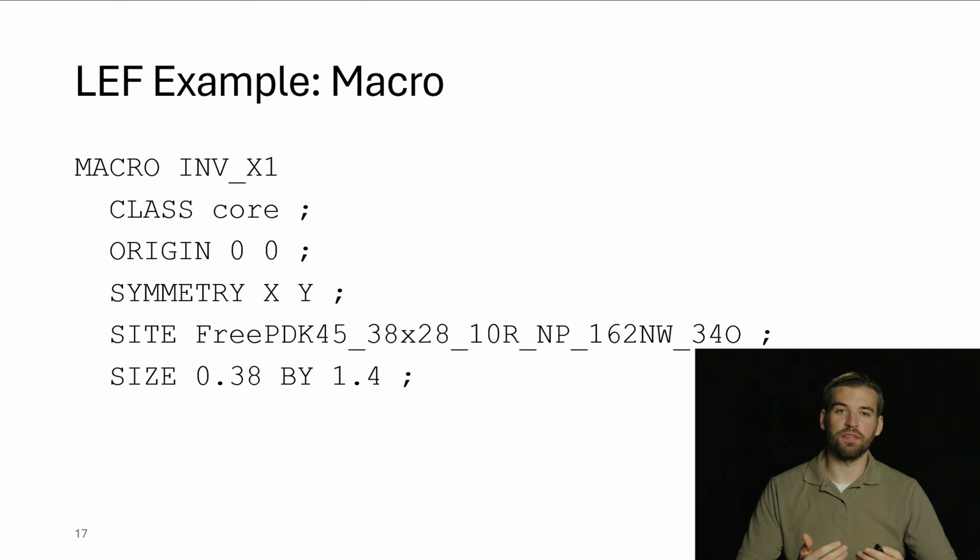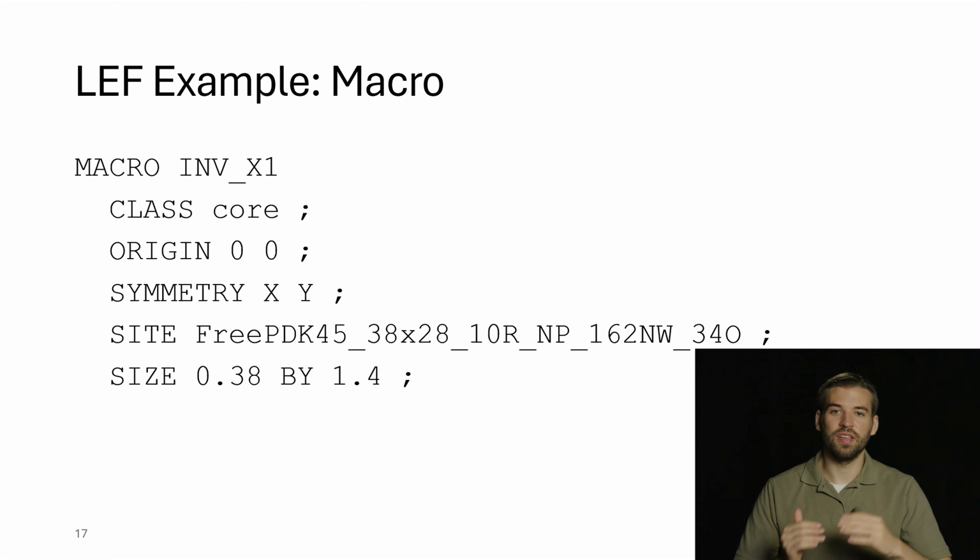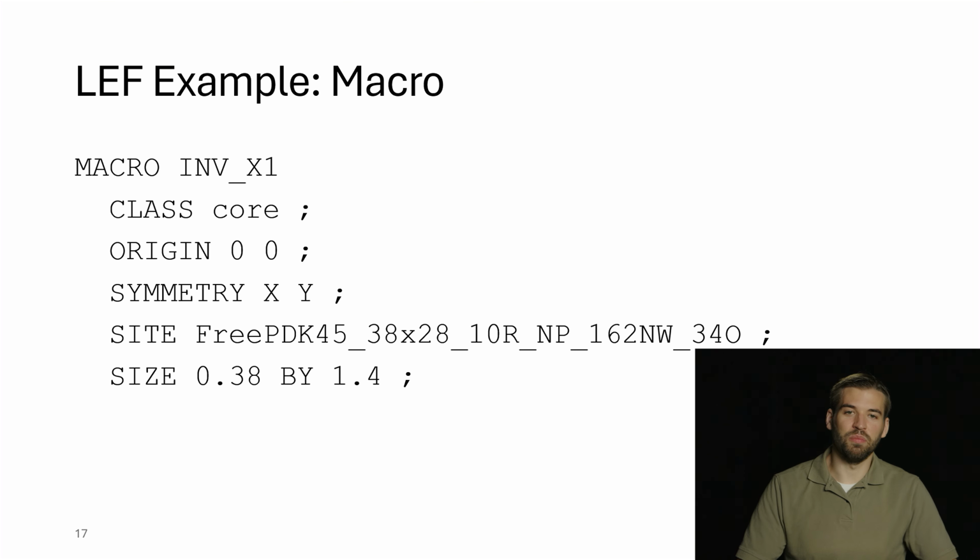In the library LEF, there isn't much preamble to it. Most of that is in the tech LEF. Here we have the macro inv_x1. Again, macro in this context is a LEF syntax, but it's going to be master in OpenDB. In Liberty we had cell, here we have macro, but in OpenDB we have master.